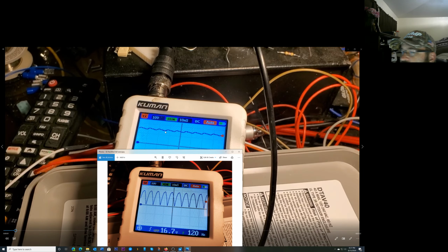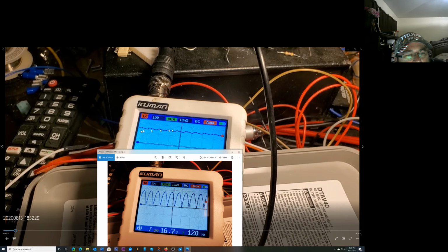So that's the capacitor. This is normal. You're always going to see a ripple once you have a load hooked up. It can't be flat because it has to drop down below here for this to even charge into here again. This is your capacitor bank, and this is what's coming in. And so this is what it looks like when you add the capacitors.